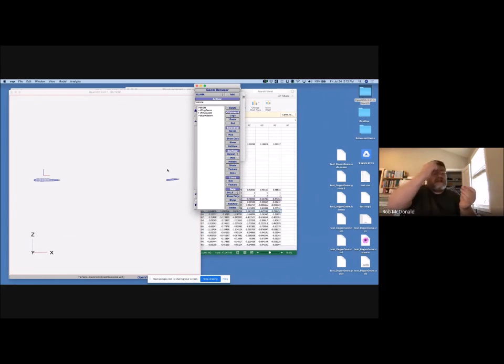Not only that, if you can get a friend to throw it backwards and you stand where you can watch its flight from the side, you will not only see it flip over, but when it flips over, you will see it oscillate and that oscillation damp out. And that's what we call the short period mode of an aircraft in flight dynamics. So you'll learn about that in 2 years. That short period mode is its static stability. And the more stable something is, the quicker that'll damp out. You don't want to play darts that way because it doesn't damp out fast enough to get a good accurate target. So I don't recommend it for winning dart matches, but it is a really cool demonstration.